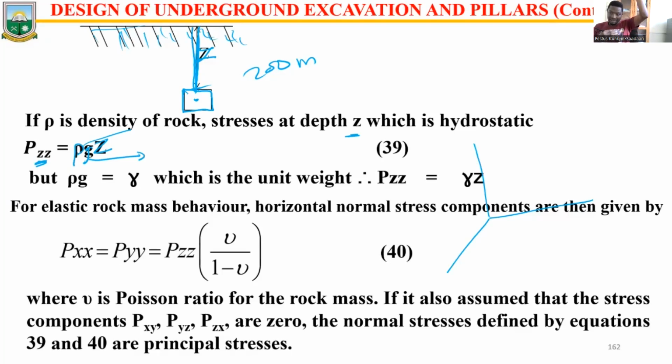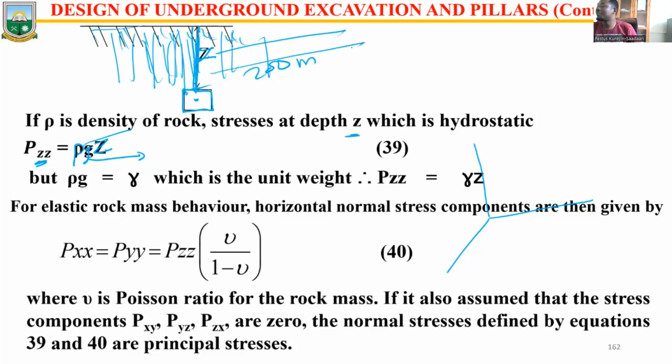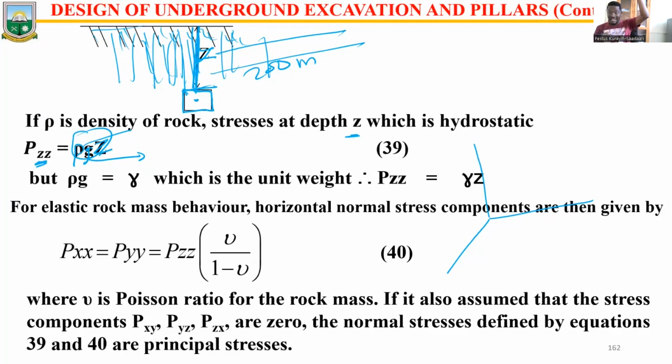that is acting on that hanging material, which is this material here. The force of gravity. So you need to know the density of the material here and the force of gravity, which is a constant we know, and then multiplied by the distance, the depth at which you are considering that material. These three components together will give you the pressure that will be exerted on the material. So for example, if this space you created here were to be a pillar, this is how much pressure you are exerting on that particular pillar.